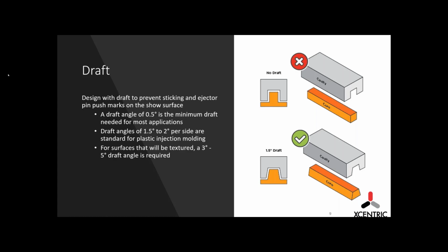What is a good rule of thumb for determining the decision to go with either a slide or a pickout? That's usually driven by the project. Usually pickouts are for lower volume prototype, form function type parts. Anything that's, I would say, 500 pieces a year or less. Once you get above that, you want to start looking at automated slides, actions.